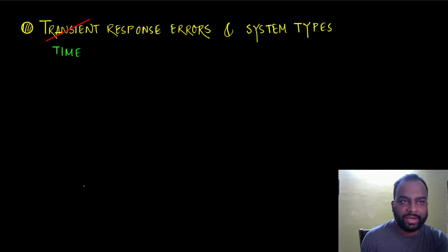We actually had a private discussion on designing a proportional controller using a simple root locus technique and Python. And you have certain auto tune or PID auto tuning modules, in case you want to design an adaptive system where you would have auto tuning PID controllers, and that can be achieved using Python, in fact in real time.